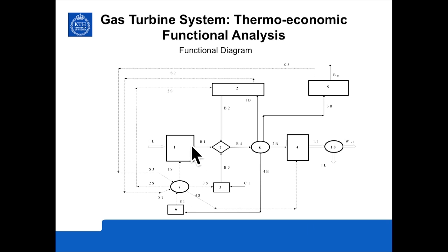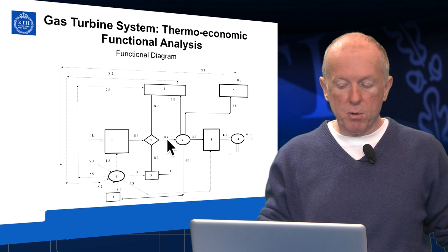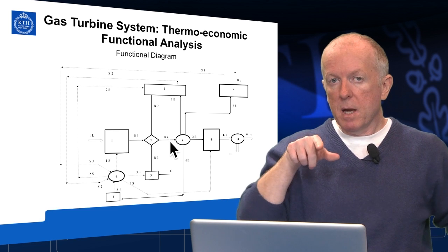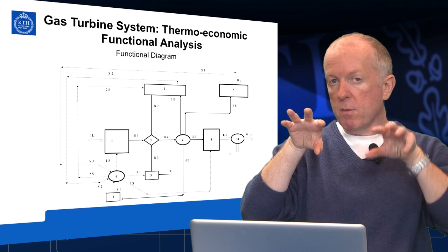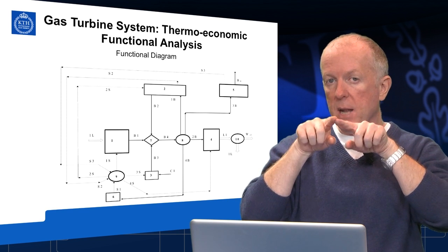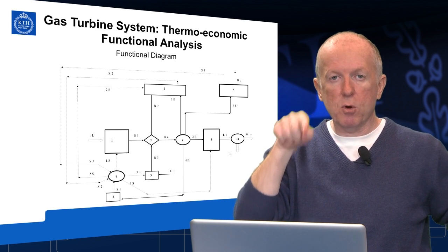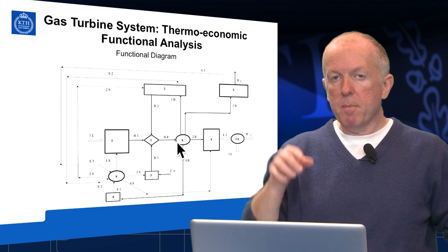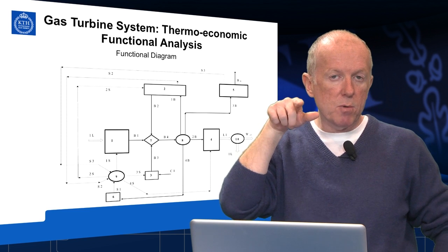So all the exergy products of the compressor, of the air preheater, and of the combustor are merged in the junction number 7. The junction number 7 produces a global product B4, which is the exergy accumulated by the compressor, by the air preheater, and by the combustor into the stream of highest thermodynamic value in the system, which is the inlet of the gas turbine. So the stream B4 is the point of highest exergy value in the system.